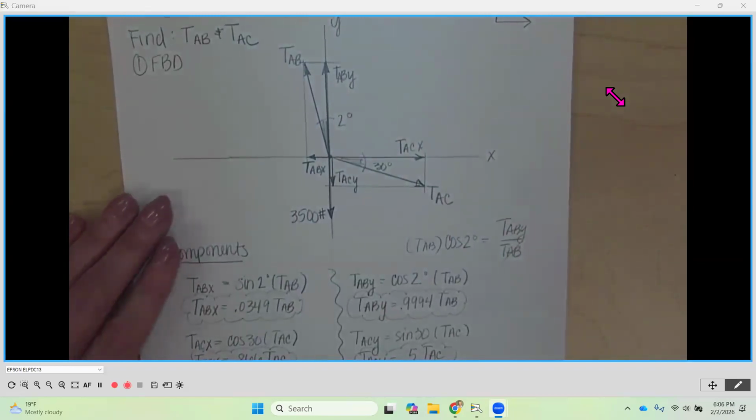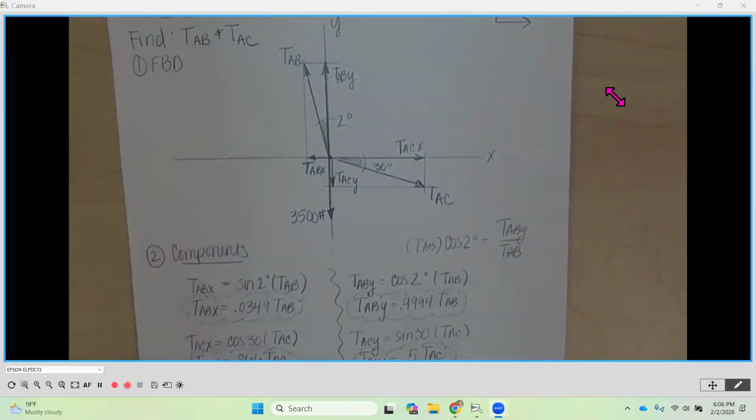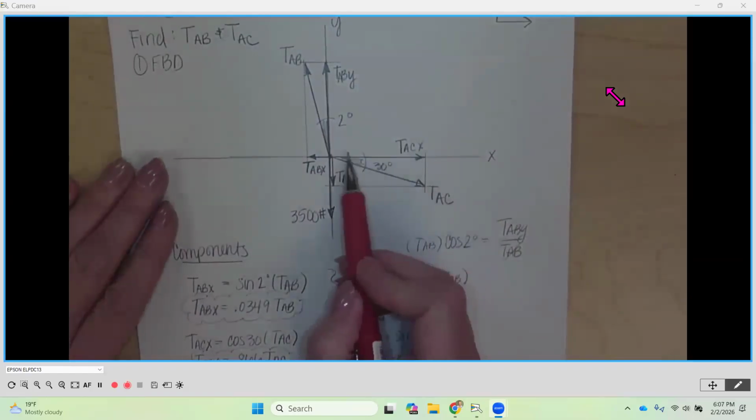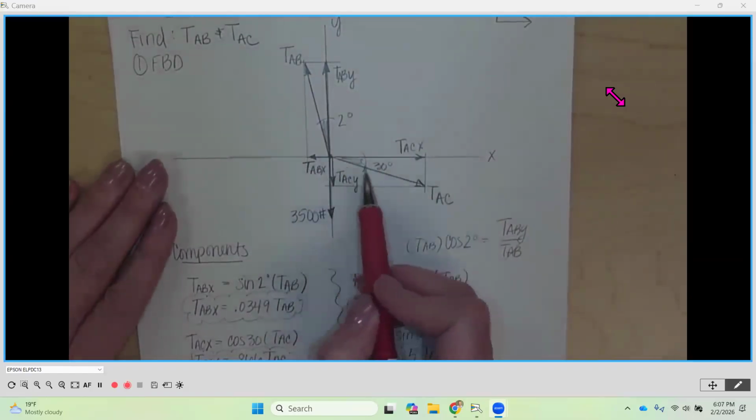You might be like, yeah, no, duh, Kelly, but you will be surprised what I get to see. And I think in math classes, they allow you to do that to visualize where the force is. But in actuality, the forces are on the axes. So make sure you draw them there. Don't float them for me, okay? So you should see two forces on your x-axis.